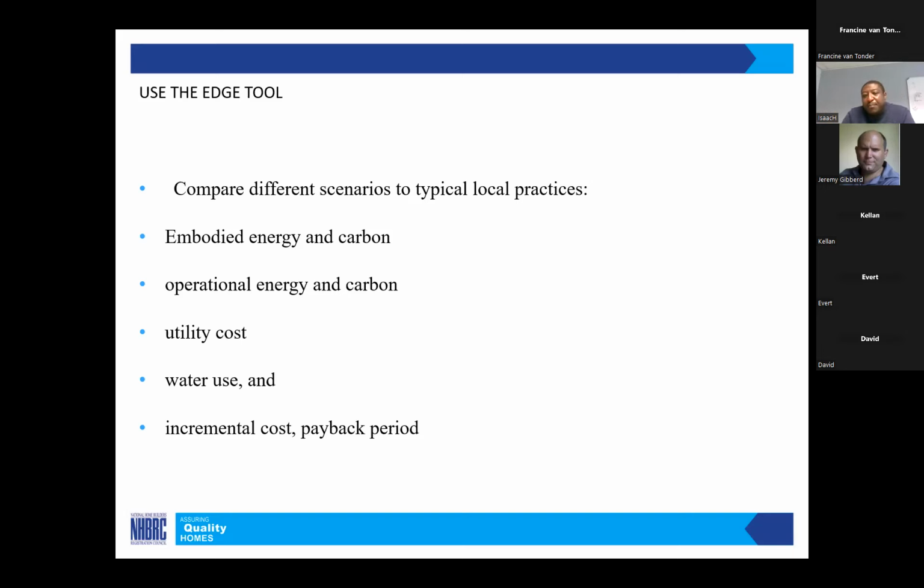Then we have performance criteria, which Agrement tests on certain materials to make sure that they can perform for a specific purpose. So I want to draw the students to SANS 10400 A20, regulation A20, in terms of houses, whether the material that they use is suitable for housing, because you find that in A20.